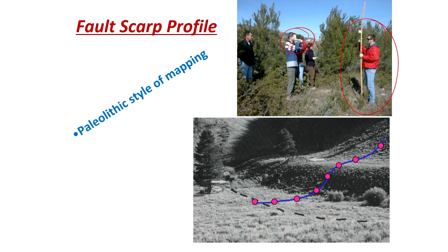Now, the important point here is the dots which I was showing. This is a scarp, and the dashed line shows the trace of the fault on the ground. Whenever there is a displacement, this topography will develop. If I put a section here, this surface and this surface were the same before the earthquake. You have a flat surface here, and because of the displacement this has gone up.